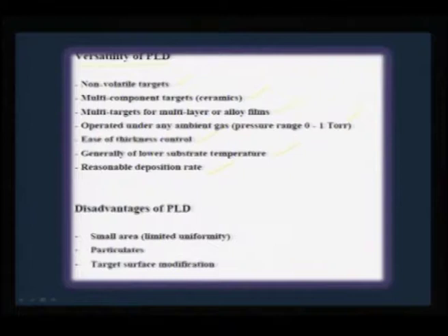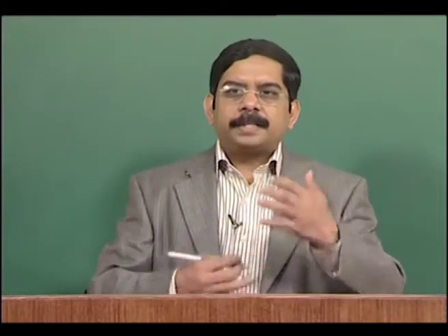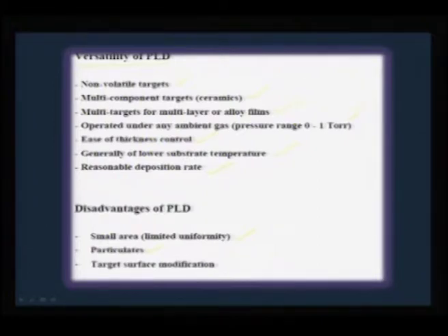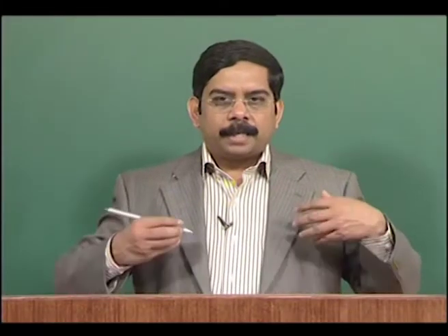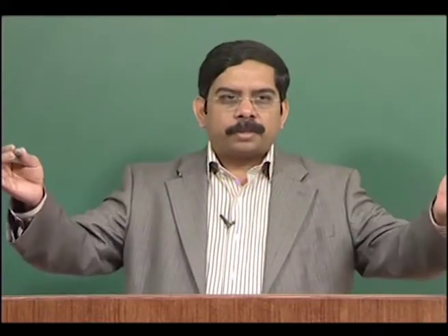Disadvantages are, if you are trying to transcend this to larger levels for large area depositions, it's not possible. So even to make a 6-inch wafer, it is very difficult, but people are aiming at such large area depositions. Because of the energetics involved in this reaction, usually you end up with some sort of particulates sticking, meaning some chunks of material can also be thrown out along with a very good layer growth. Therefore, this can become a problem.